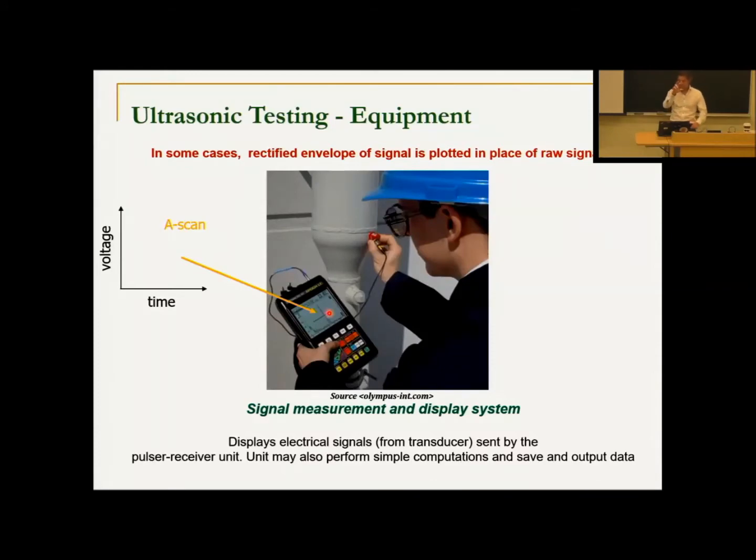It could be a crack, and by taking different measurements, a good inspector will be able to locate and size and characterize that crack. We call this single voltage versus time signal an A-scan, right? So this is a very common first-order ultrasonic inspection. Very portable, applied readily in the field, but the inspector has to have the expertise to understand what the signal means and interpret it, right?